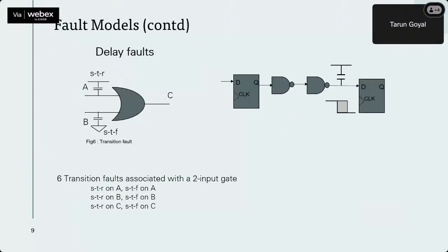So taking the example of the delay fault, suppose this transistor is not stuck but it has capacitance, it will be slow to rise, so we call it STR, slow to rise, and then maybe slow to fall also. So this is kind of an expected behavior. It may come delayed, like a slow to fall kind of behavior. So that kind of transition faults we have.